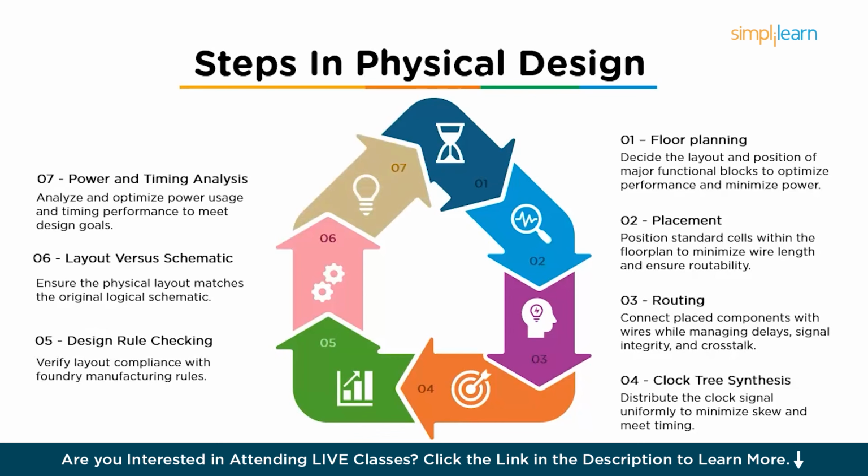Then comes power and timing analysis. So the power and timing analysis checks ensure that the chip meets performance goals like timing closure and power consumption. So the designer uses static timing analysis (STA) tools to check for timing violations and optimize the design.